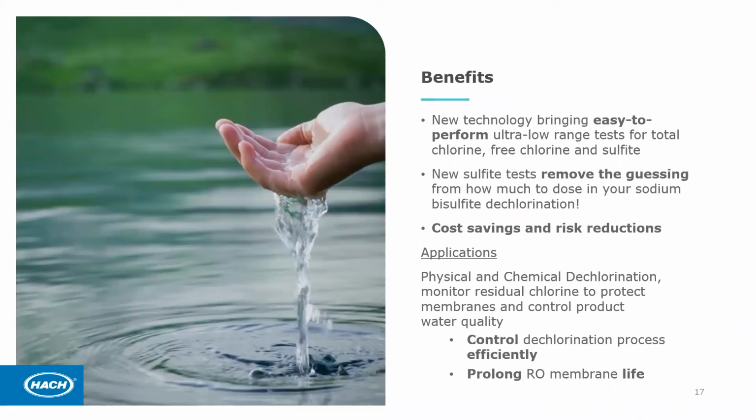These test results can be obtained using very easy to perform tests. So I would argue one step more complicated than a traditional powder pillow test. We are taking a small amount of sample, putting it in a somewhat standard test tube, and adding, using 2 dropper bottles, 5 drops of each reagent.